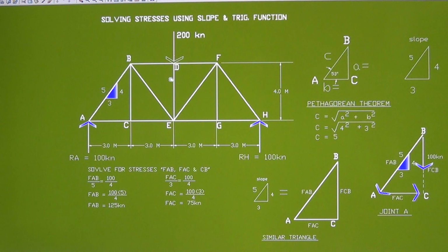See, when the load is applied, this load pushes this bottom chord down. You're gonna have deflection right here like that. So therefore, when deflection is going down, all these members here will sustain a tension. Since it is restrained here, fully restrained, it's not gonna move. And here, when this load is applied, there's a tension going on here.